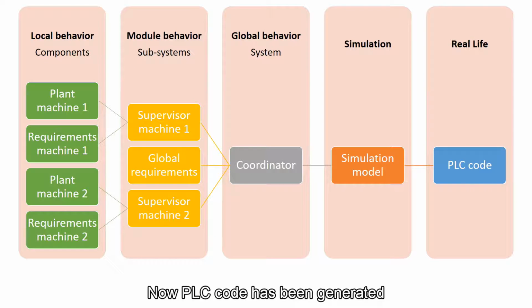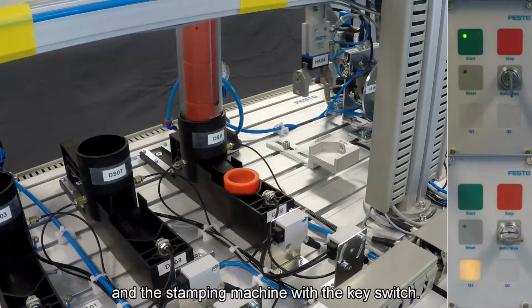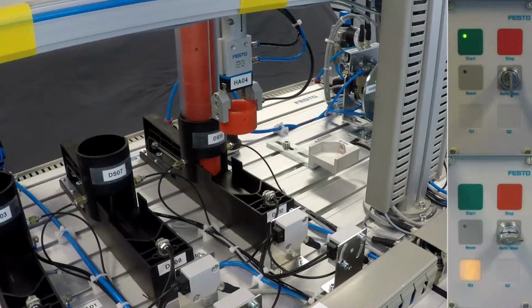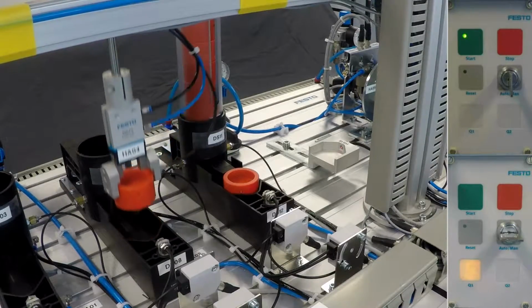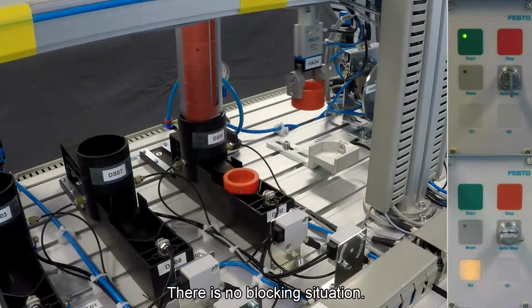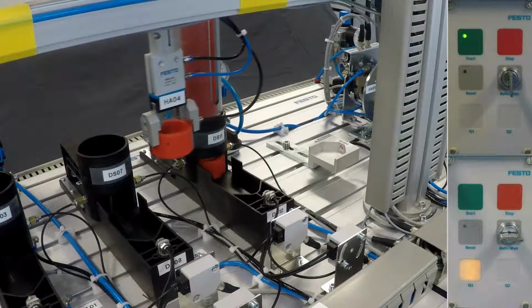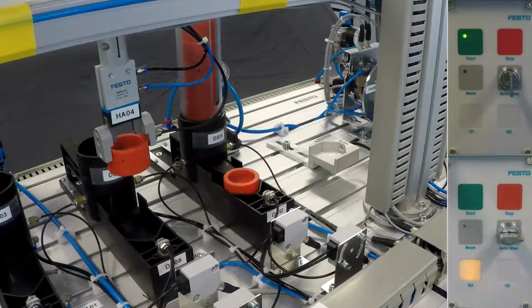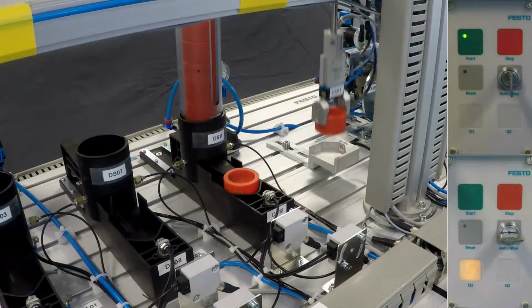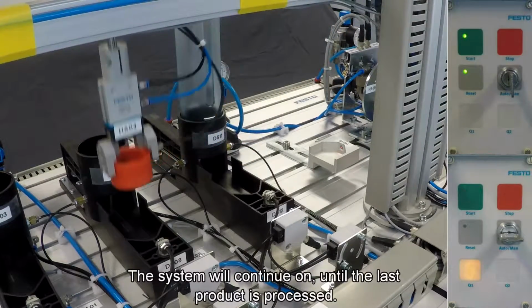Now PLC code has been generated and the controller is examined in real life. The product dispenser is activated with a start button and the stamping machine with the key switch. The system works as required. There is no blocking situation. The system will continue until the last product is processed.